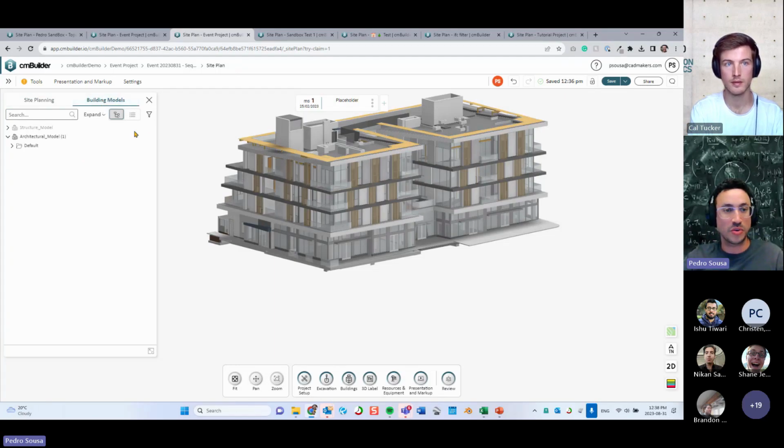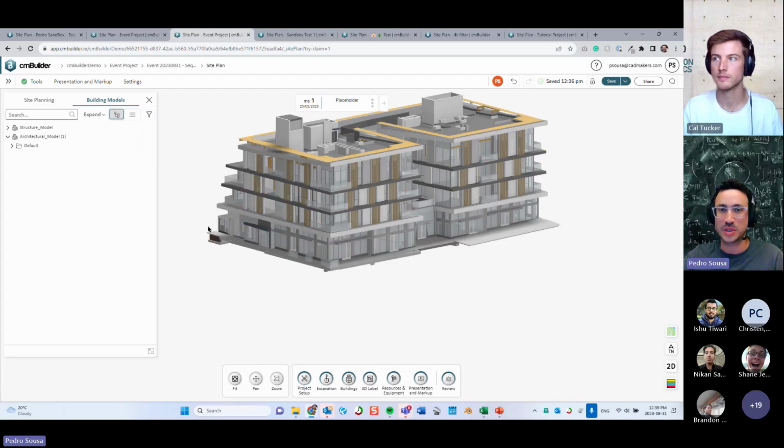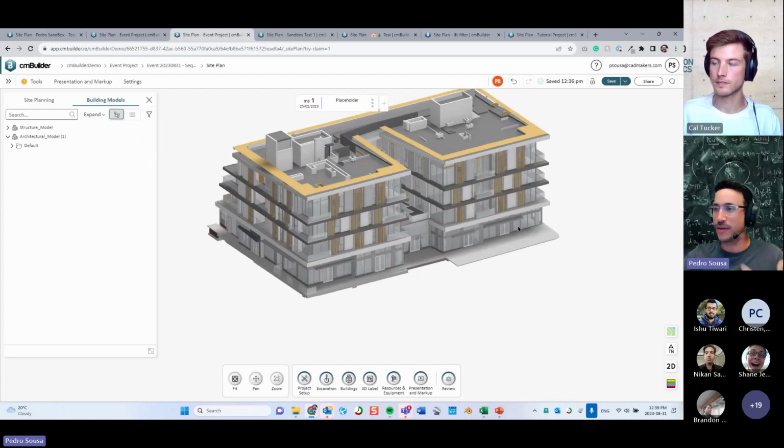And also from the selection tree, I already talked about this, but the IFC filters is a very, very good friend whenever you're working with an IFC file, because it will allow you to filter your view by that IFC class, using the story and so on and so forth. So please use that whenever you want.